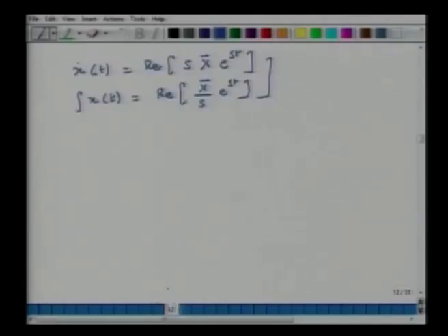So, and then if I have to find velocity, I know complex displacement, so I just differentiate it and take its real component. This is my velocity. If I have to integrate x, all I have to do is divide that by s. So that's all I'm saying. So we'll do an example.